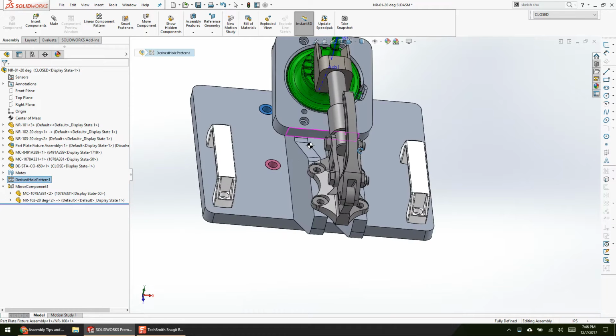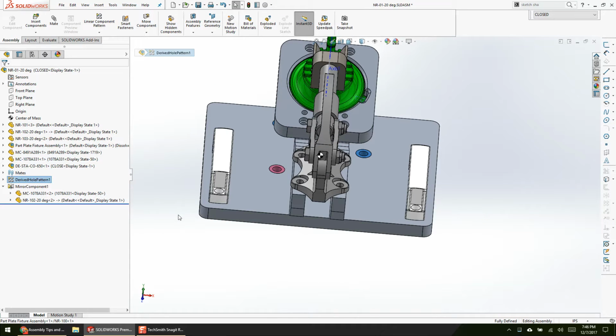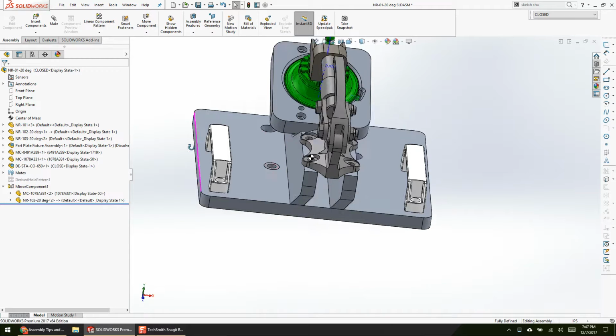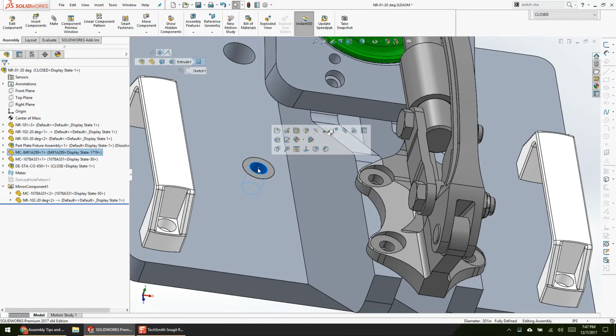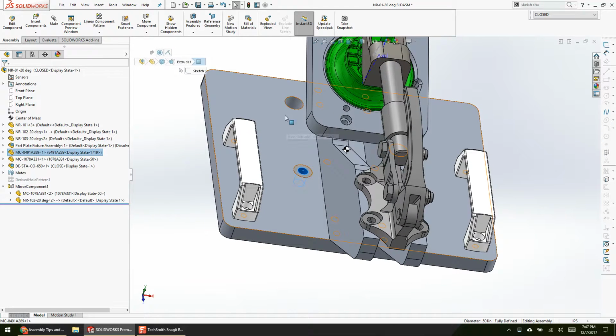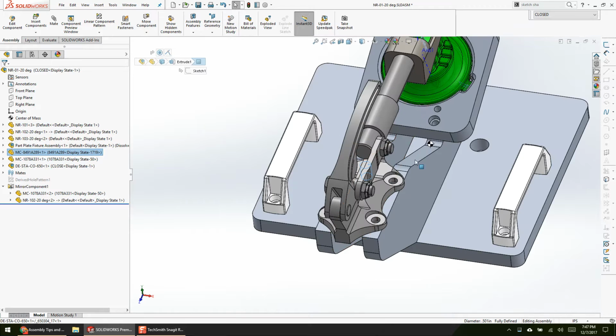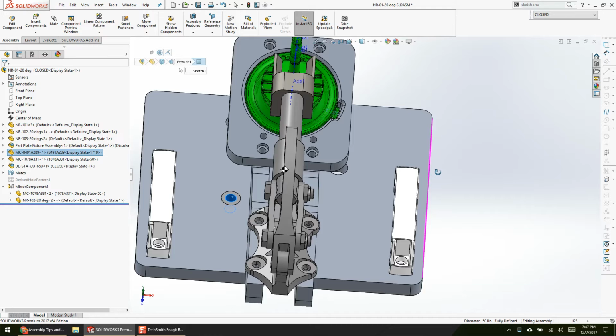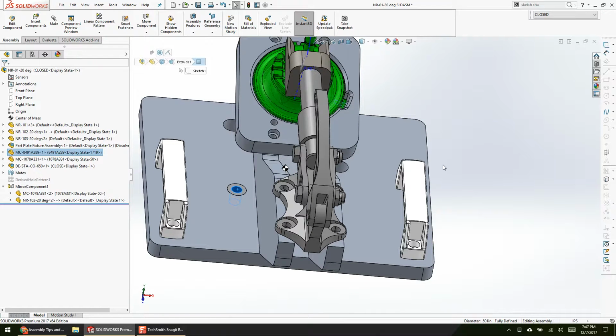And then we also have another awesome feature that, for some odd reason, is not very popular. Not a lot of people know about it. But I'll suppress this feature again. I can't, so here's a bushing. I can't mirror my bushing very well because I don't really have a good plane, and this bushing hole is not mirrorable, right? It's some random spacing that's idiot-proof, so you can't put this on backwards. So the design has been idiot-proofed, which makes an odd pattern that isn't mirrorable or like a linear pattern.